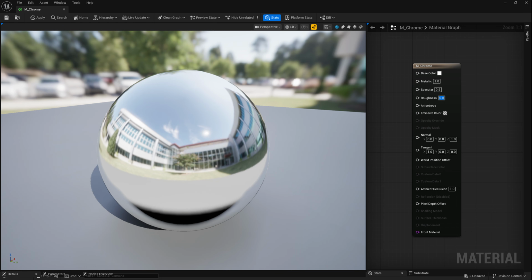You can have materials mixed in the PBR workflow using masks, wetness on top of something, or oil on top of something, or having a clear coat on top of something, but these things are generally approximated in a PBR workflow. And this is where Substrate excels. Substrate is a shading framework or workflow that allows for more of a modular system where you can stack and blend multiple materials where each layer behaves more physically correct. It's not perfect either, but it's a step in a direction that brings you closer to a more accurate result.